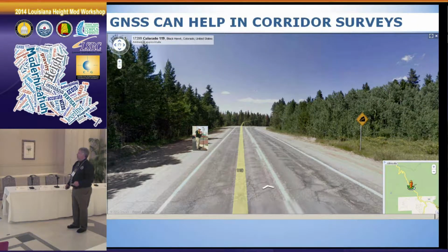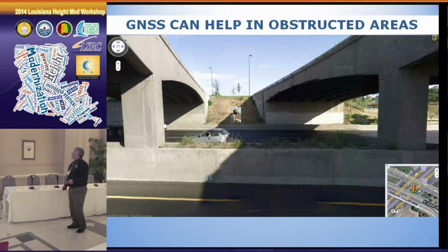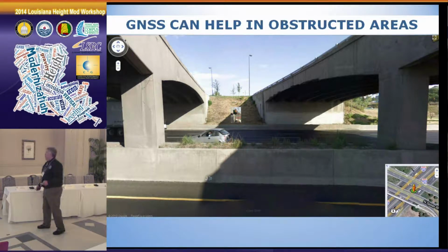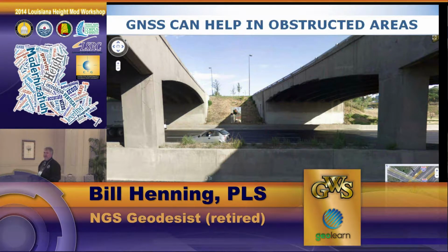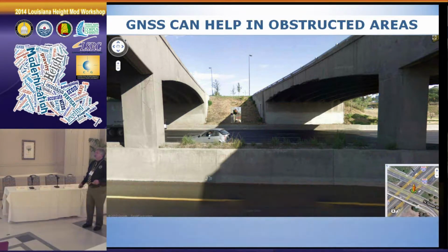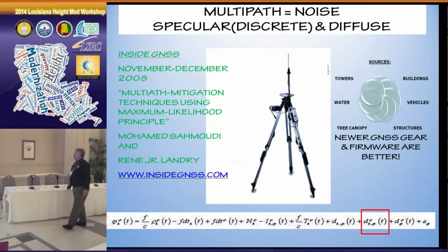And it'll help you in urban canyons and areas of the highway with trees where you have to get an important point. GLONASS will help you in all those conditions. If you have 7 GPS satellites, you will not get a better answer with GLONASS. But you might be able to get an answer if you don't have 7, where you can't with GPS alone.